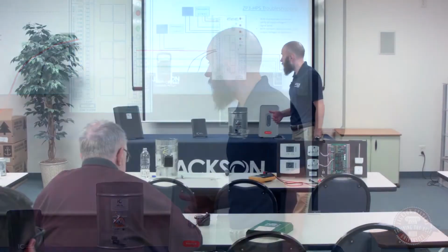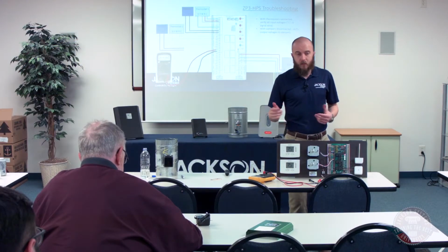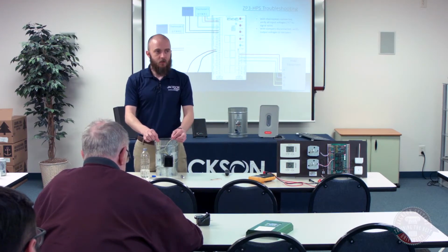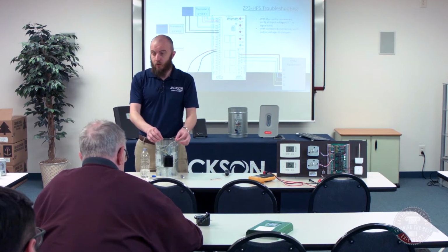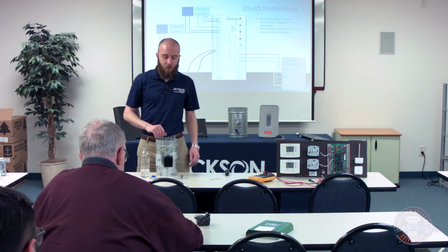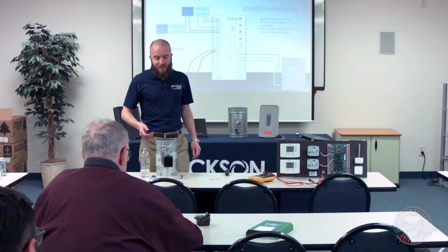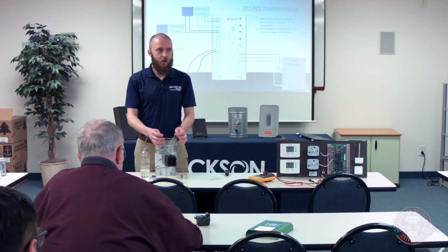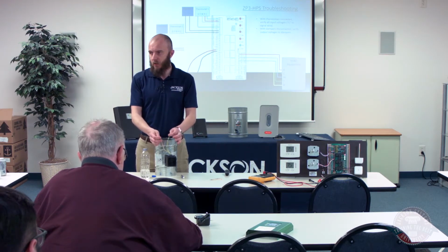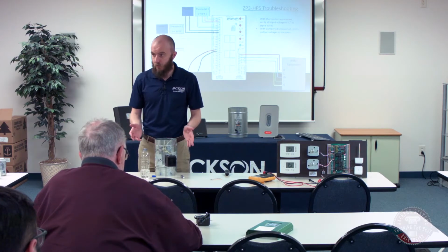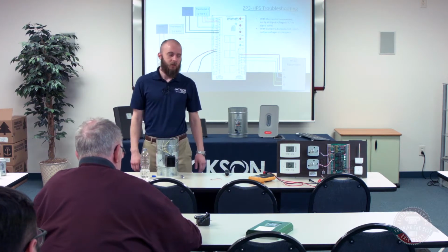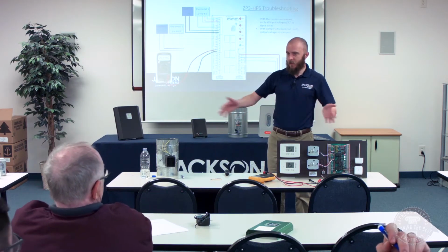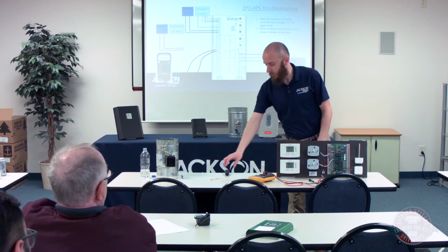If you're getting the correct output but your damper's still not working, then I'd go down to where your damper is and actually check the voltage at the damper, to make sure it's getting the right voltage there. Make sure there's not a broken wire somewhere, or some loose wire nuts. And as a last case, if you suspect your damper actuator may be bad, you can always just get 2 wires straight off the transformer and put 24 volts straight to the damper to power it open, power it closed, and see if it moves. If it doesn't, you probably have some issue with the damper. But again, it breaks down to just breaking the system apart, testing the individual components on their own, and knowing what to expect.